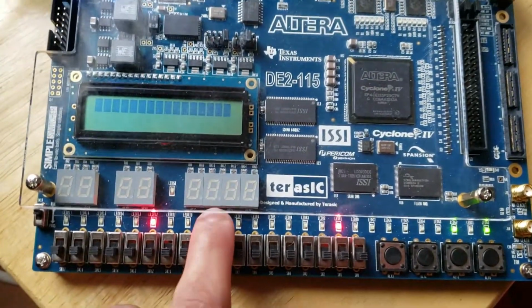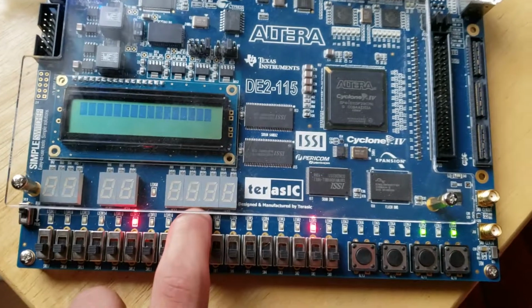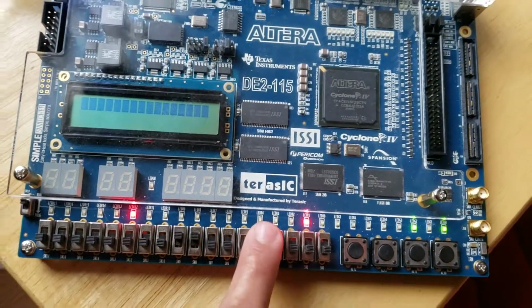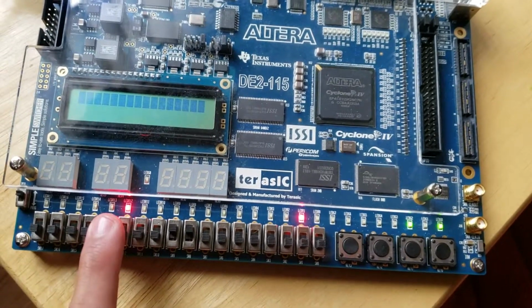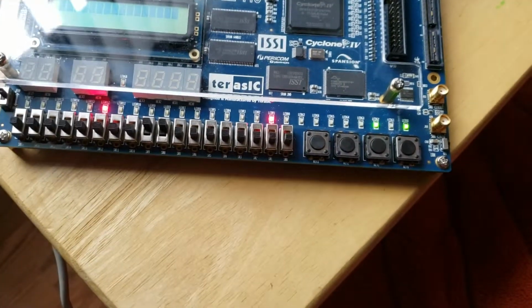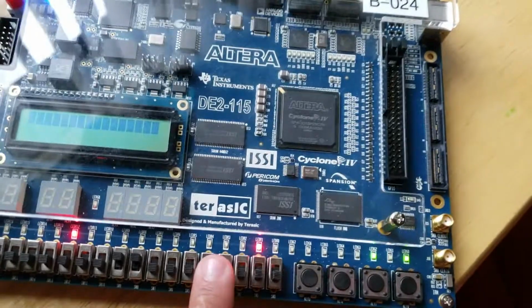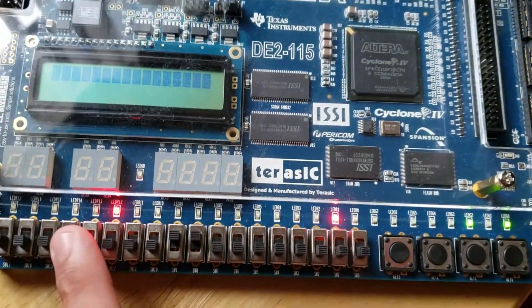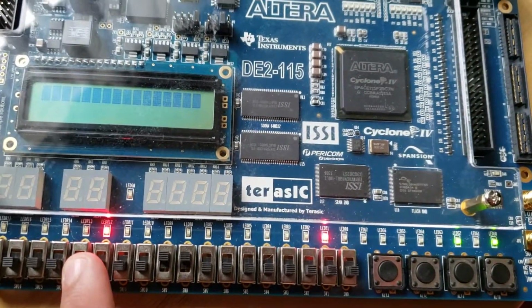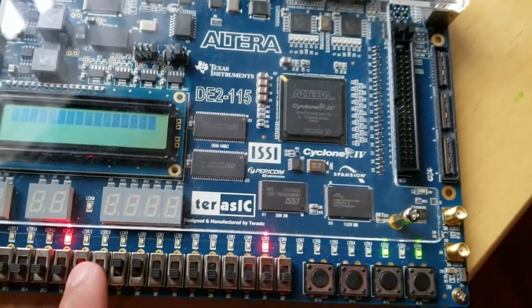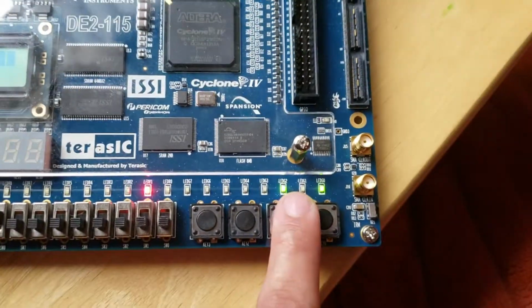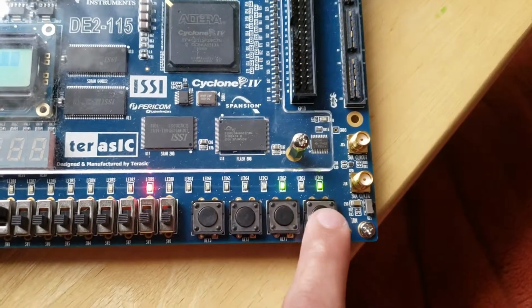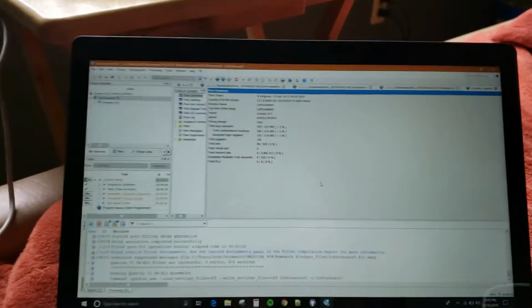But right here, this separates both values. This is RD1 and this is RD2. We've done our own calculations where RD1 has an exponent of 2, and then RD2 has an exponent of 4. Now, the final result has an exponent of 5, which is 101. There's an overflow when they add it, so the exponent gets shifted, or one added to it.